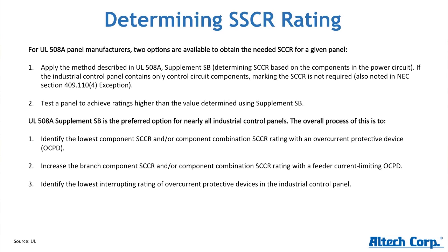Unfortunately, most of these methods then will bring you to a lower short circuit current rating. So when you install this panel, you then have to make sure that your SCCR rating is equivalent or better than the available short circuit current rating at your installation site.